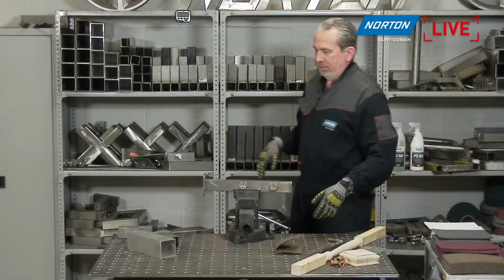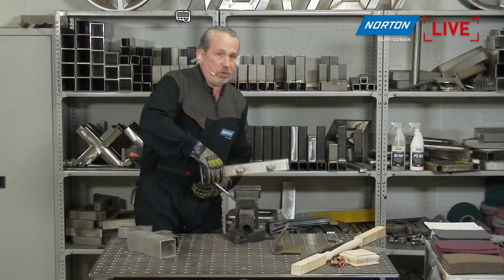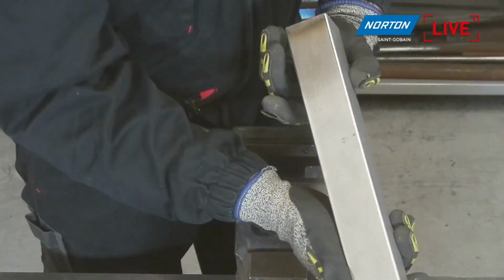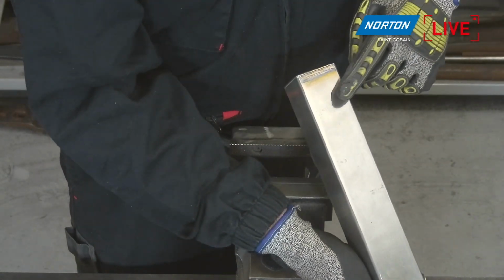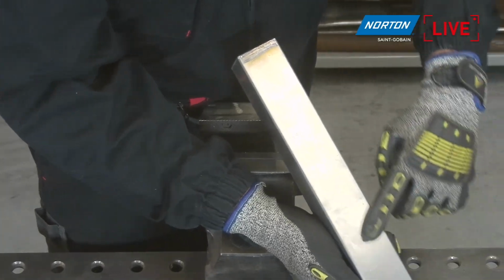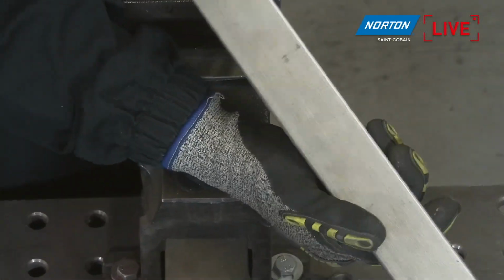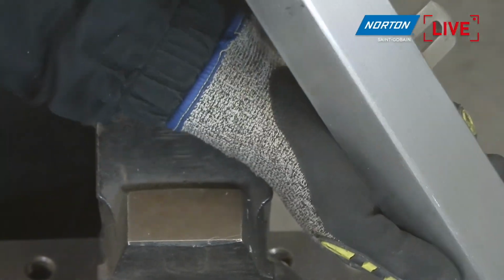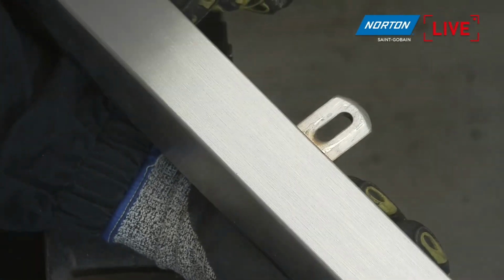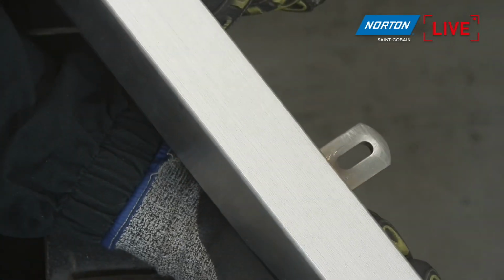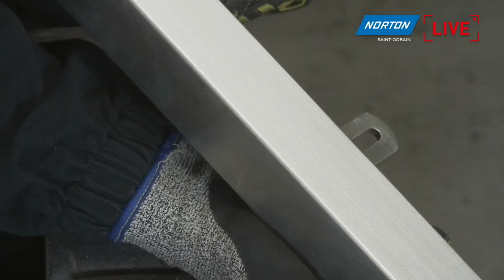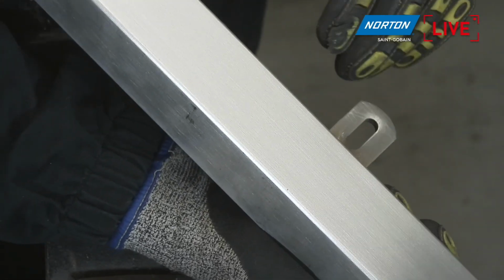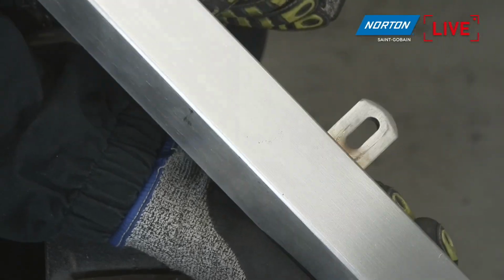That's a really quick finish. If we have a look at what we started with, we started on the surface like that with a dark weld here and lots of damage from transport and being around the welding shop. And we get this really, really quickly. You see, a nice linear scratch, which is perfect for stainless steel applications, again, just to show less fingerprints or less muck or damage as it's in service.